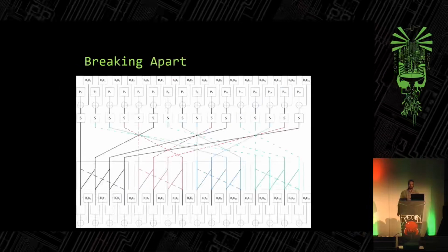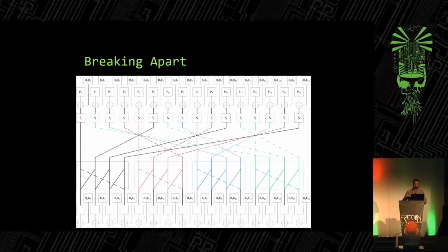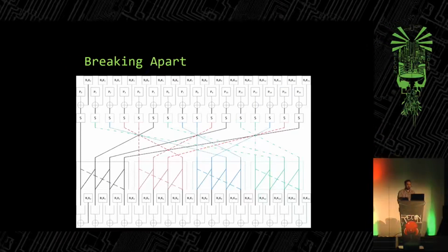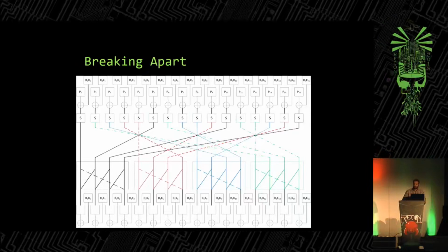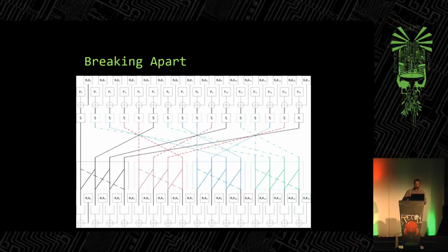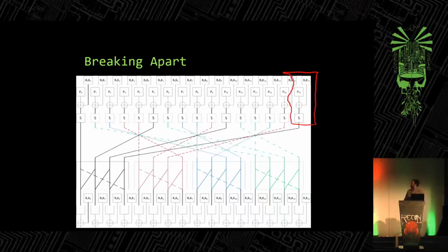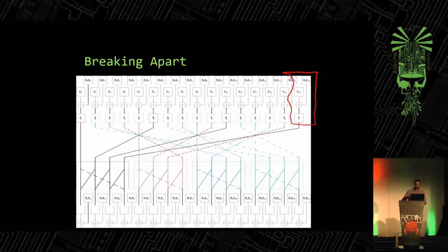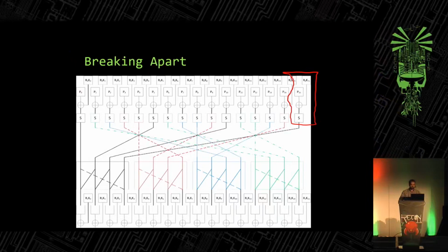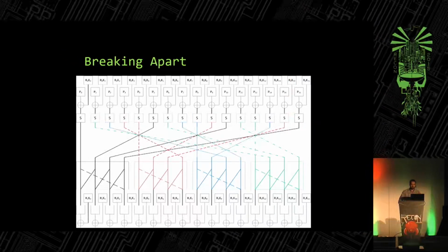Why this is useful to us is if we look at a lot of algorithms, so again, going back to AES, it's a 128-bit key, so we can't guess the key any way we want. But what we could look at is, well, it operates on 1 byte at a time. If I just draw a crude rectangle around that section up there, what the power analysis will tell us is that we're going to look just at this point in the algorithm.